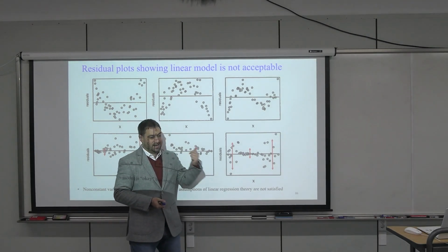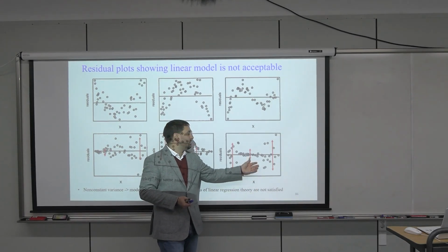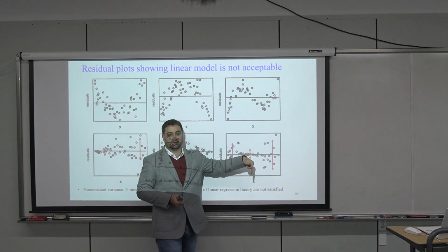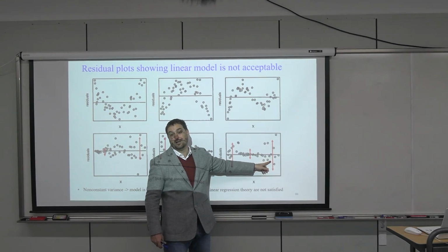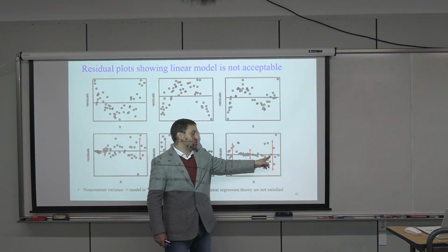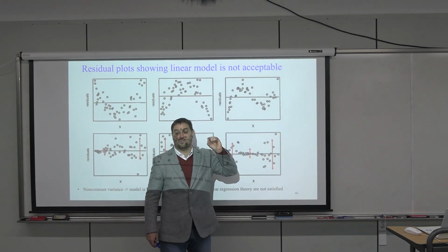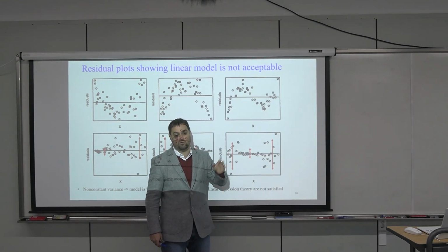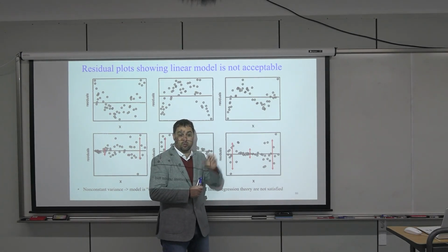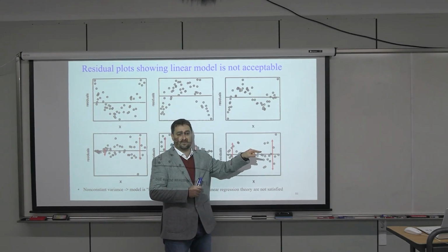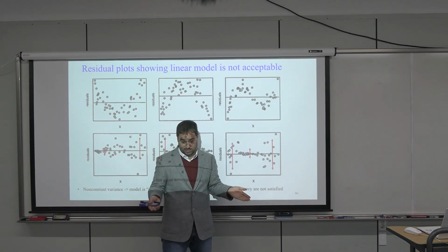And so as you increase velocity, or in this case X is velocity or flow rate, you're in turbulent flow, but your pressure is decreasing. Maybe this might be what's called cavitation, where the pressure of the flow is now less than the vapor pressure of the fluid. So let's say you have hot water at 95 degrees Celsius, almost boiling, you keep increasing the velocity, and that water will start to boil. That's called cavitation.